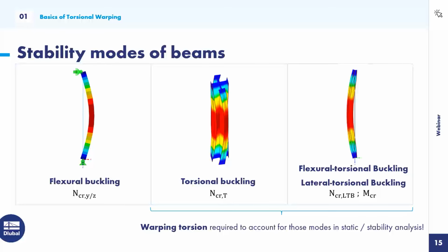Because only with 7 degrees of freedom, the kinematics of the beams loaded in bending, axial force, and torsion are properly taken into account. And I want to show you another example where this is quite important, and it is not related to this case of torsional stability, but it's maybe a much simpler case that you and I would probably stumble over in regular analysis.